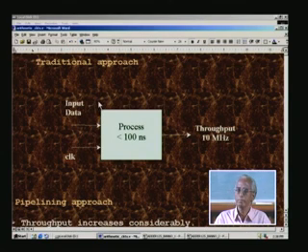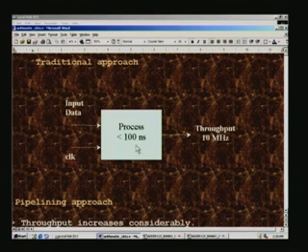And before we go for the pipeline approach, let us see the traditional approach. For example, we have a multiplier, and let us say it takes 100 nanoseconds or a little less than 100 nanoseconds. Then what do we do? If it is a real time application, we need to apply input data periodically, let us say with respect to a rising edge of the clock, and at every positive edge of the clock you need to input data, and out comes the processed output here.